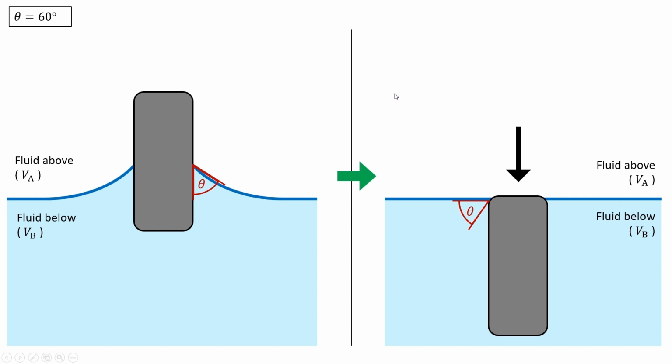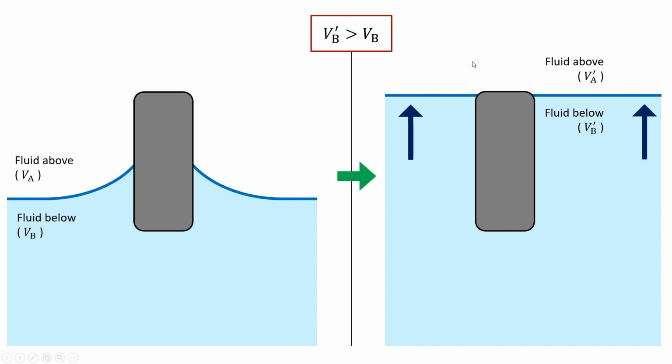In Interface Equilibrator, we can mimic this behavior by allowing volume exchange between the fluids during the equilibration. Indeed, if the equilibrium shape of the fluid interface is computed without keeping the fluid volumes fixed, then the volumes of the fluids will automatically adjust themselves so that the fluid interface reaches its equilibrium height with respect to the solid particle.